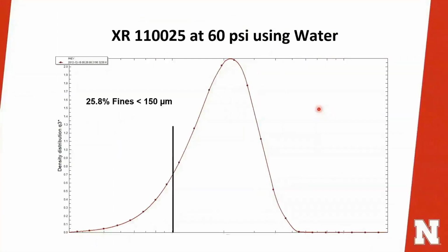One of the things that we do in our lab out there in Nebraska is to understand the droplet size of different nozzles and tank solutions at different pressures. We have a laser diffraction system there that tells us exactly what droplet size we're spraying. So we did this series of simulations with different nozzles and pressures, so you can understand how important this is if we want to mitigate drift.